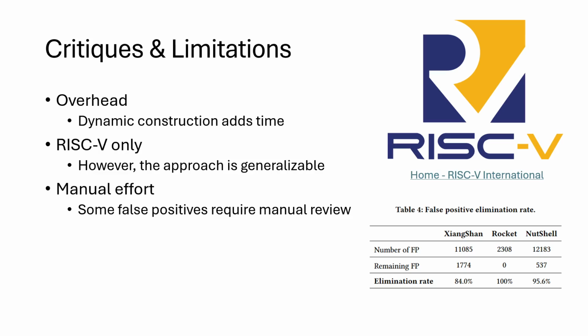Secondly, DiveFuzz as it currently stands only works with RISC-V processors, so the concepts could potentially apply to other instruction sets, but the actual implementation is currently only RISC-V. And then lastly, you do need some manual effort because of the false positives. Despite the fact they have the false positive eliminator, there are still some that need manual review.